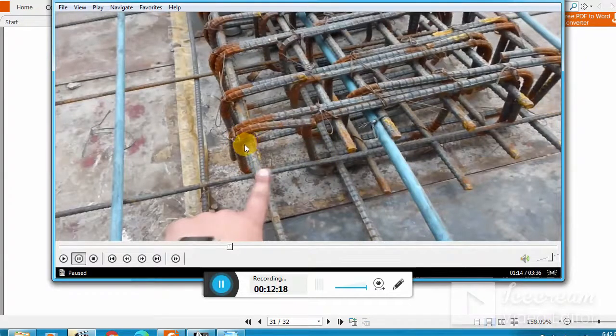Remember, if you have 6 legs, then you have to place 6 horizontal bars, and these bars are the same bars as we are using in the slab as flexure reinforcement. So 6 bars in the top and 6 bars in the bottom. Similarly, we are using 2-leg stirrup, meaning we have 2 legs, so we need 4 bars, 2 in top and 2 in bottom.